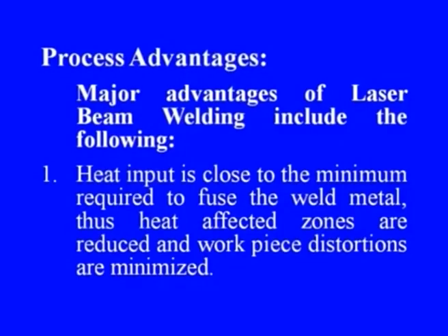Now, let us look at the major advantages of the laser beam welding process. Number 1, heat input is close to the minimum required to fuse the weld metal. Thus, heat affected zones are reduced and workpiece distortions are minimized, as we have already spoken about. This is also a thermal based process, so a heat affected zone is likely.